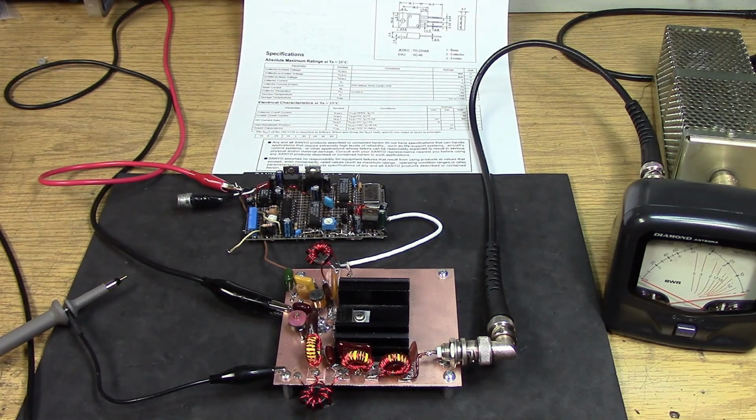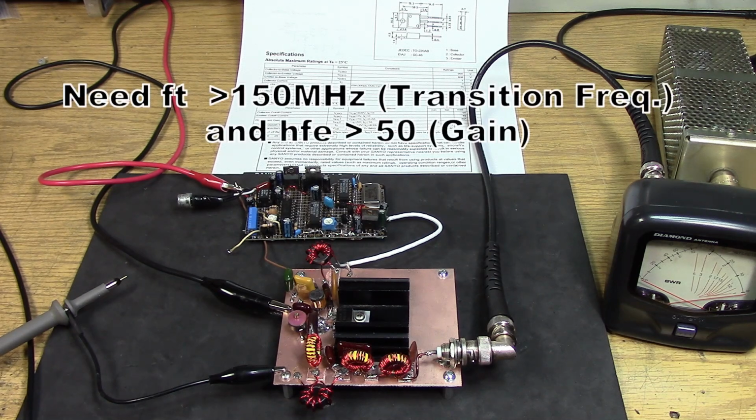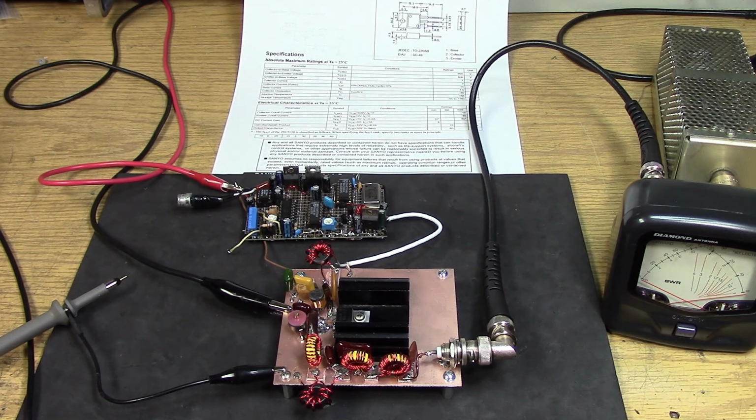So probably not a good choice for a Class E final. Probably should have a transistor that has an FT that's at least in the 100 megahertz range or higher. And it doesn't have a lot of gain either. If you hit it with the switching pulse, I'm sure it'll do something. But one thing we have to be really careful with bipolars compared to FETs.